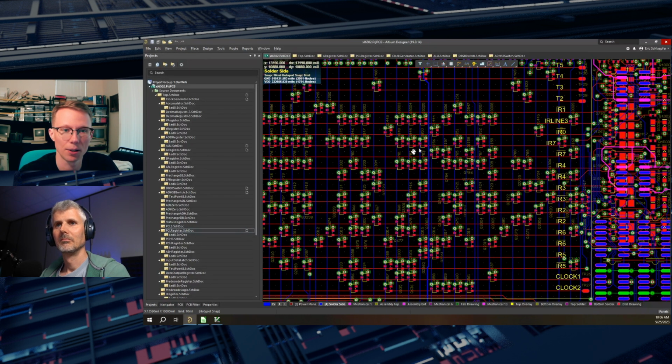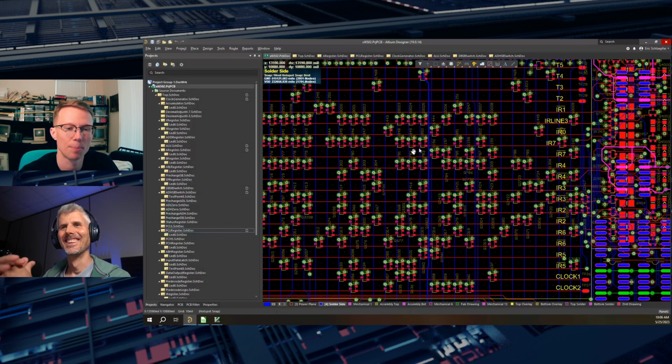I could also tell that the board was heating up. Since I don't really have a good thermal camera, I could get a vague idea of where on the board it was. But to narrow things down, I wound up using a piece of Scotch tape. Those super buffer transistors melted holes in the Scotch tape, and so then I knew what was going on, or at least I could progress to the next step of troubleshooting.